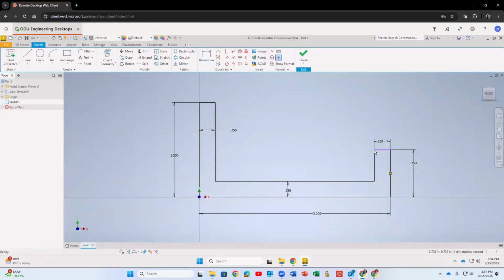Let me see. If you see purple, I can try to move. Okay, you see, if this happens, that means I just need to say that this line is horizontal. You see my x-axis is there, so I can just say, this is horizontal. Can you please make this and this horizontal? And you see now it added that constraint.